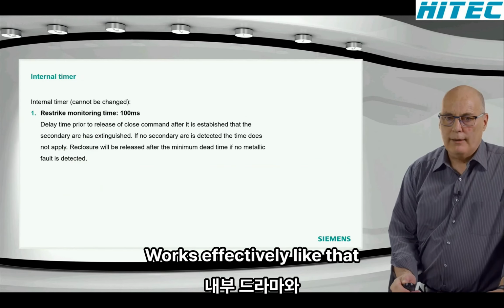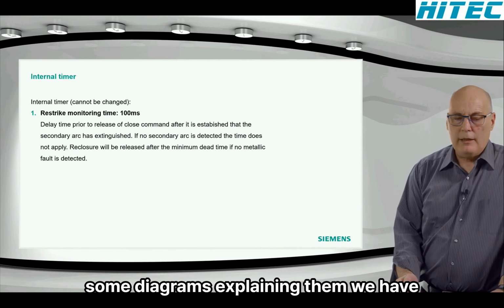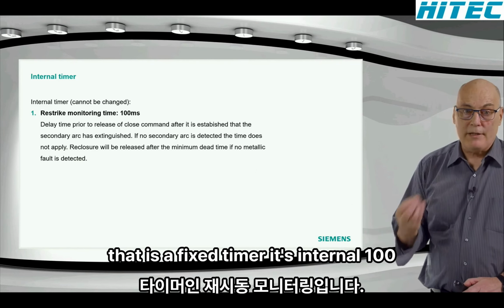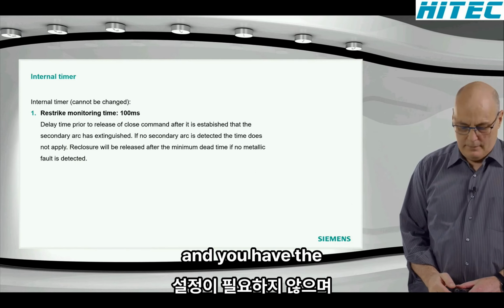Works effectively like that. The internal timers, as I said, I'll have some diagrams explaining them. We have the two timers. There's the restrike monitoring. That is a fixed timer. It's internal, 100 milliseconds, no setting required. And you have the